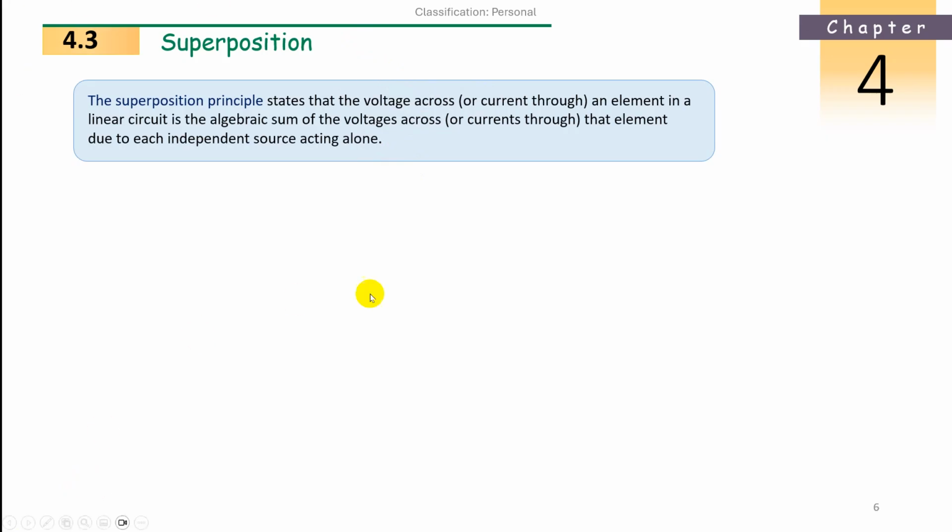This is only voltage sources and this is only current sources. Now let us take a mixed case. Same principle: if we have some voltage sources and some current sources, we remove the remaining voltage and current sources, but at a time use only one source, maybe current or maybe voltage, and start analyzing the circuit. Next step, analyze for the second source. Third step, analyze for the third source. Like this, when all the sources are finished, stop analyzing. Now add together the values of each branch voltage or current, or whatever is required as per the question.